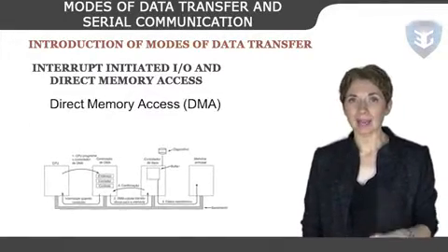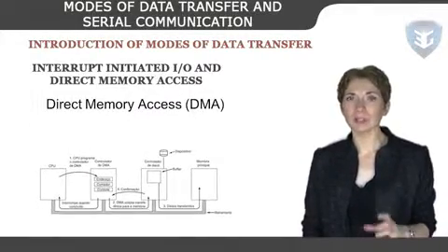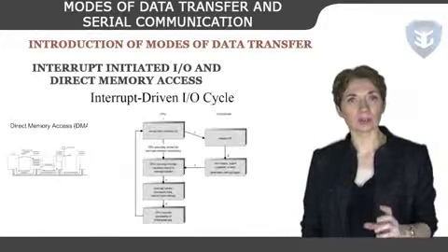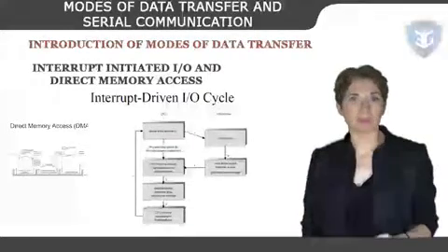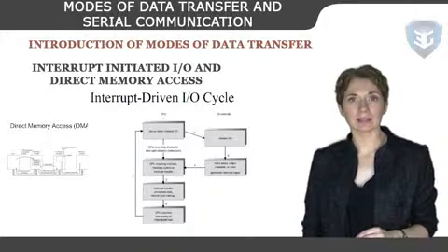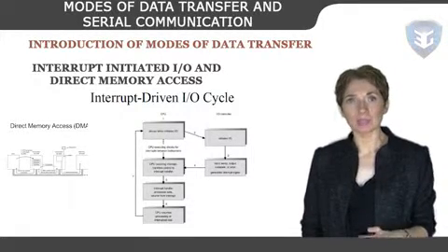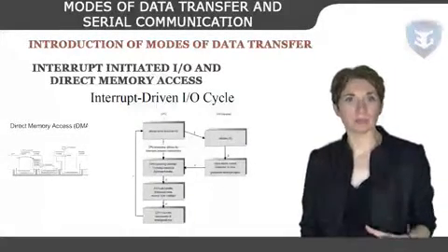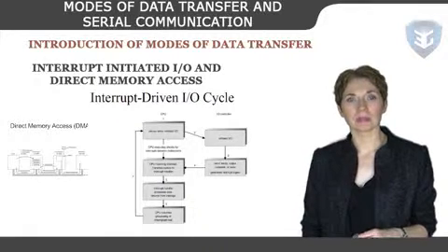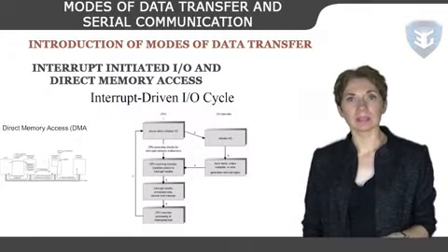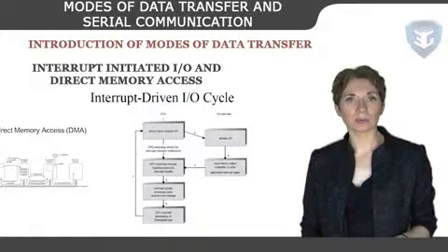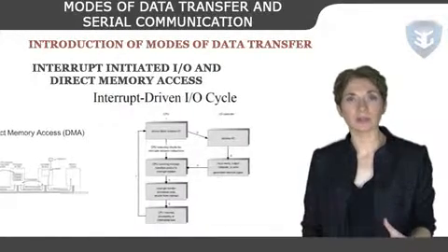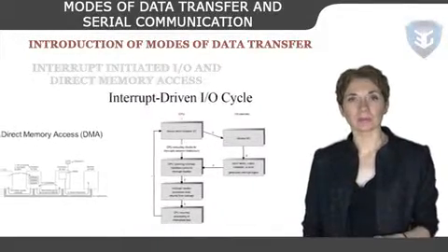However, when the flag is set, the computer is momentarily interrupted from proceeding with the current program and is informed of the fact that the flag has been set. The CPU deviates from what it's doing to take care of the input or output transfer. After the transfer is completed, the computer returns to the program to continue what it was doing before the interrupt.